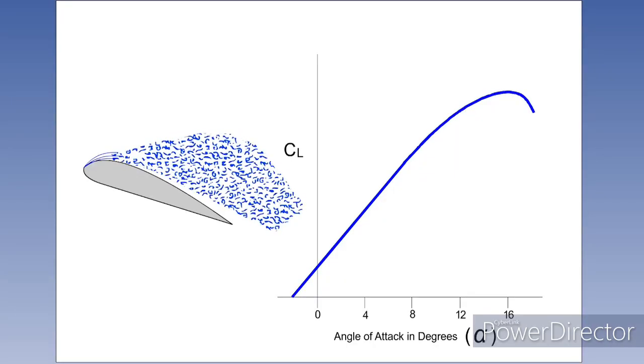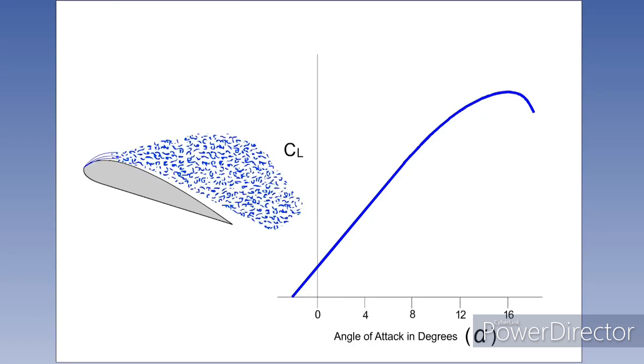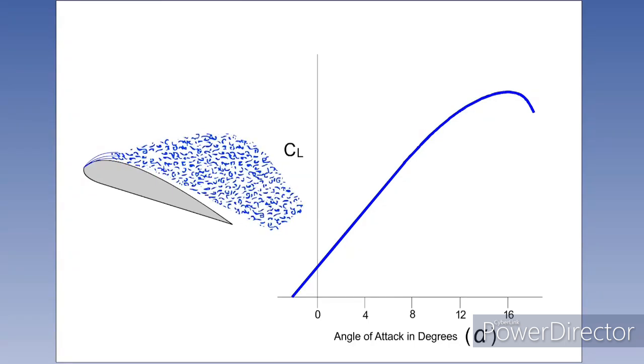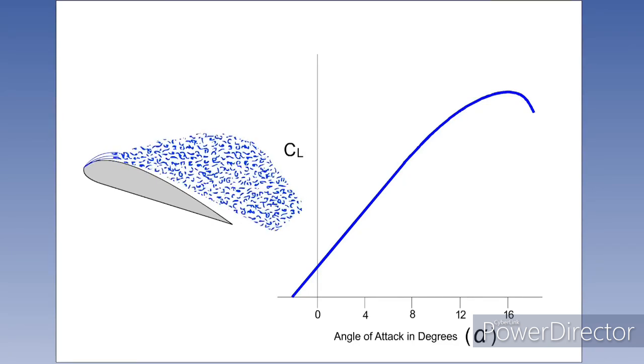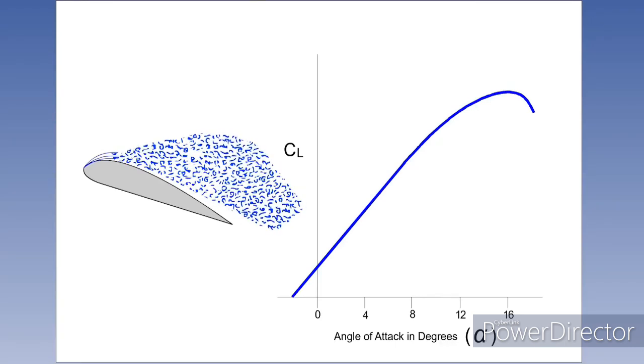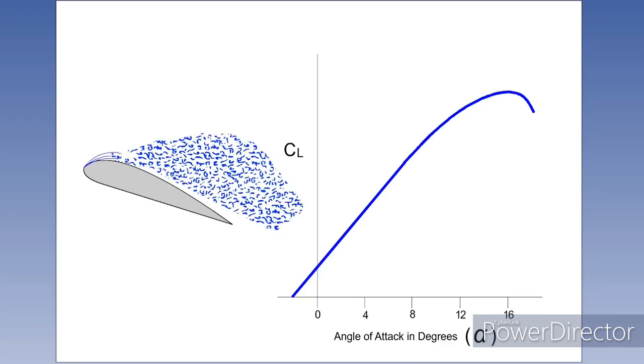You have learned that stalling is due to airflow separation, resulting in a loss of lift and an increase in drag that will cause the aircraft to lose height. This is generally true, but there are some aspects of aircraft behaviour and handling at or near the stall which depend significantly on the wing's aerofoil section and planform. The shape of an aerofoil section will influence the manner in which it stalls. Some sections will stall very suddenly, with a marked drop in lift, whilst others have a more gradual approach to the stall, with a less dramatic loss of lift.